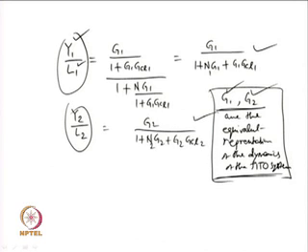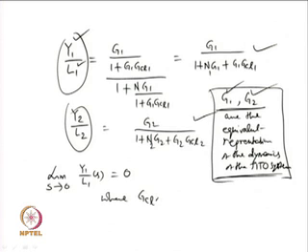So, why am I expressing this? The reason is that if you find the steady state values of the output corresponding to the static load disturbances, the limit as s tends to 0 of s times y1/L1 will give you 0 when the controllers G_CL1 or G_CL2 have integral action or integrators. When the controllers have integrators, basically one s will appear in the numerator.